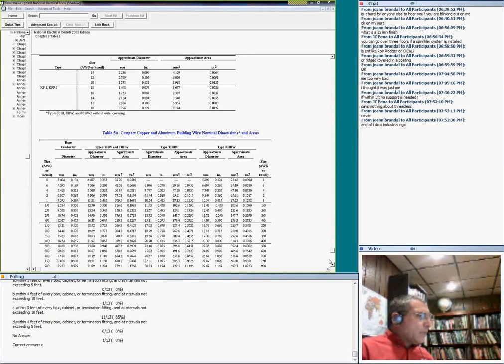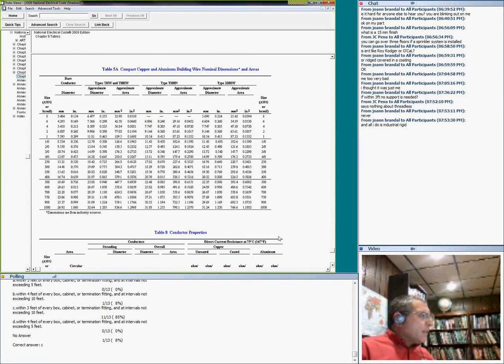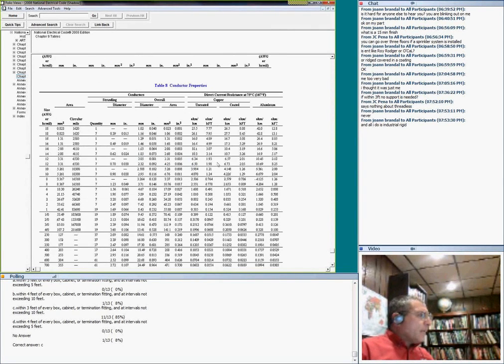If you're using compact conductors, you can get the cross-section area for them, aluminum or copper, right in here. They're not round, guys, and they basically have a smaller diameter. You're going to use them for retrofit only. You'd never use them for anything else.